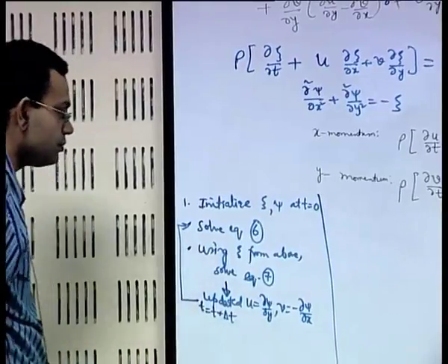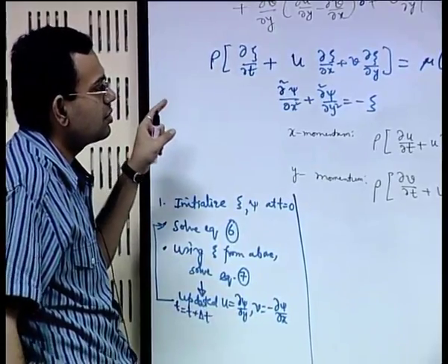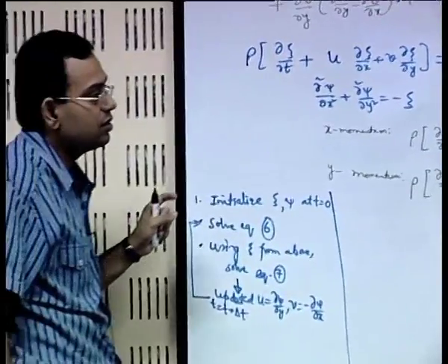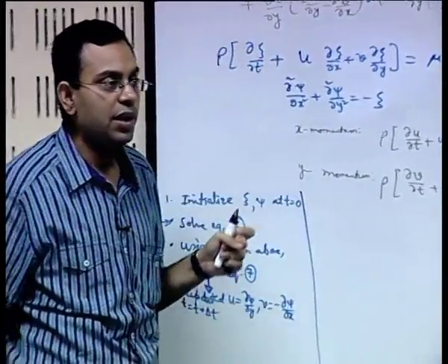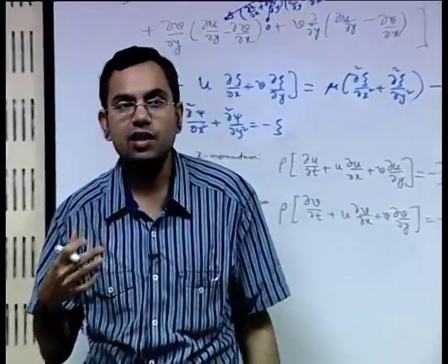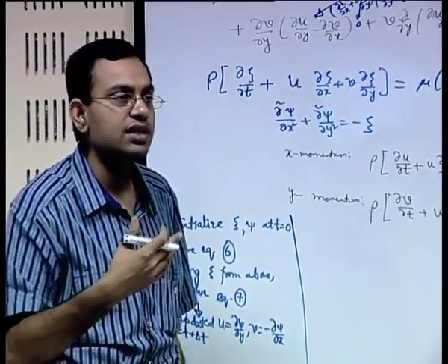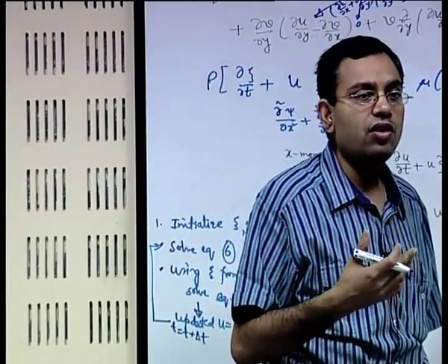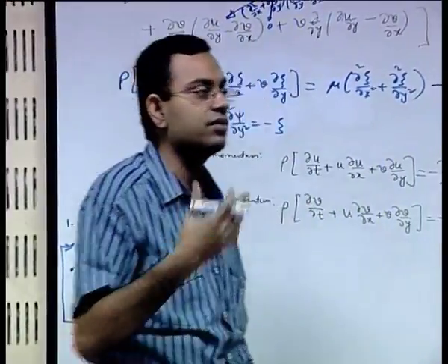Now it is straightforward to describe the solution of the stream function vorticity equation, but we have not yet discussed the corresponding boundary conditions. The boundary conditions on velocity and pressure, these are physical primitive variables. So the boundary conditions on these are intuitive, like you can say the velocity is something, pressure is something, but the boundary condition on stream function and vorticity, these are somewhat derived quantities.